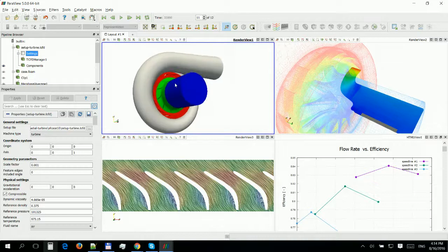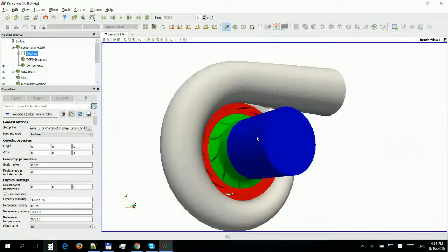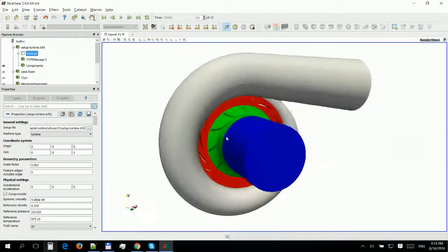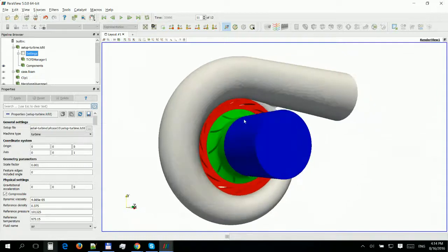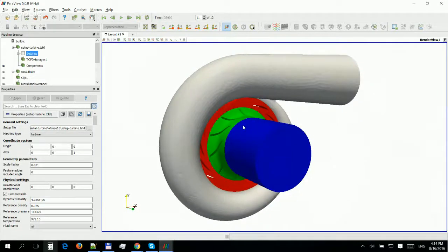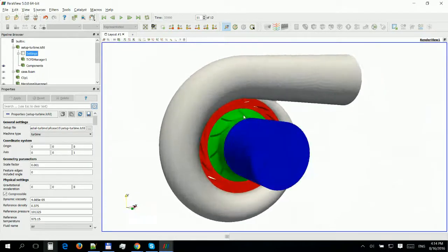So each Turbomachinery CFD simulation case has its inputs, and these are basically the surface geometry, which is 3D geometry loaded from some design tool or from your CAD, for example. It's very standard, very simple .stl, so it's stereolithography format. All CAD systems can export this surface geometry. It's like a 2D mesh in 3D. It's pretty simple.